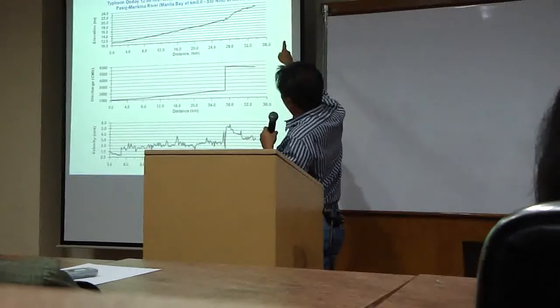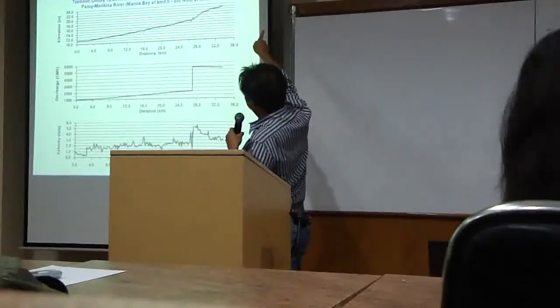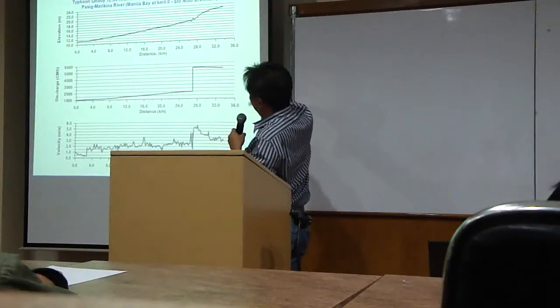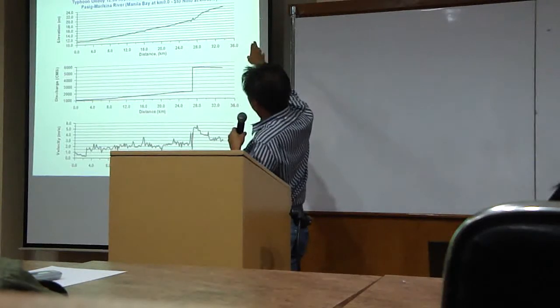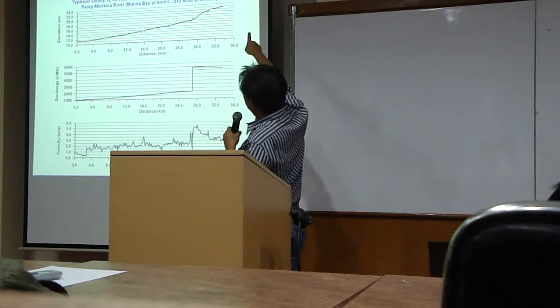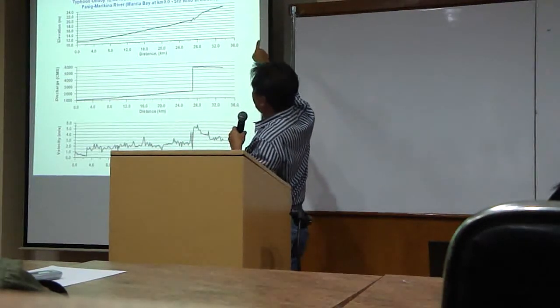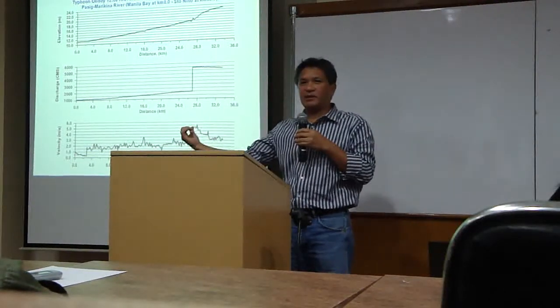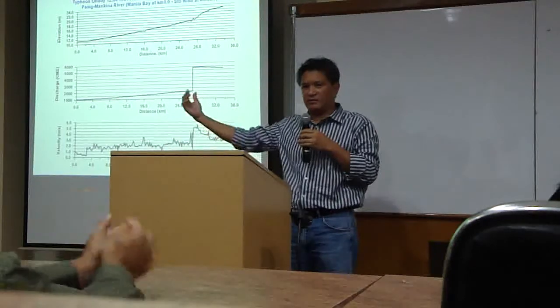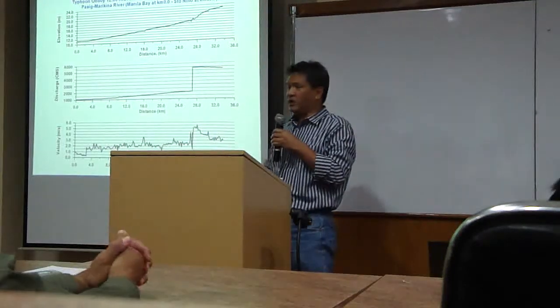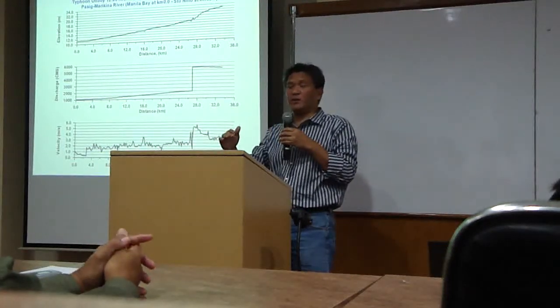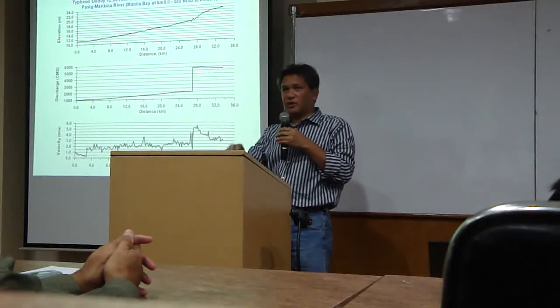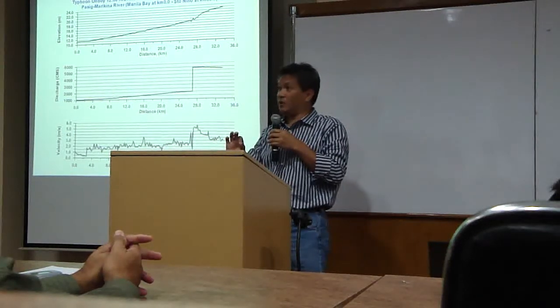So if you look at the river profile, the water surface profile, I'll show you a much better plot later on. But anyway, you have again 22 elevations of water. By the way, the datum for the Marikina River water stages should be minus 10.47 meters, so that it's 0 at mean normal water.